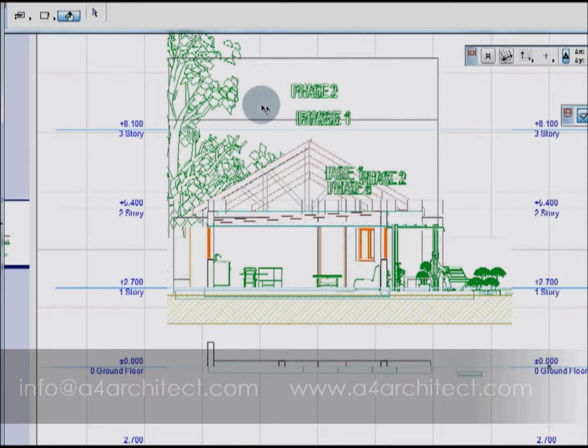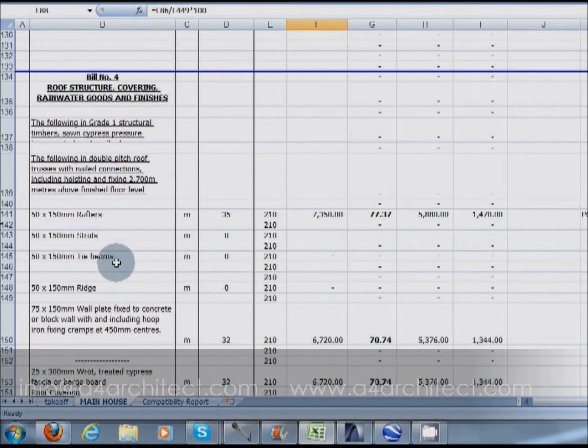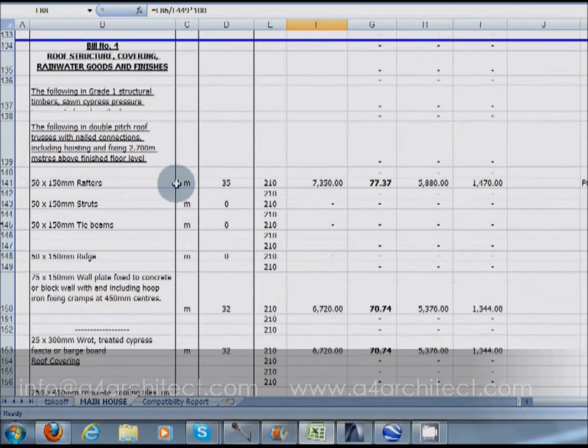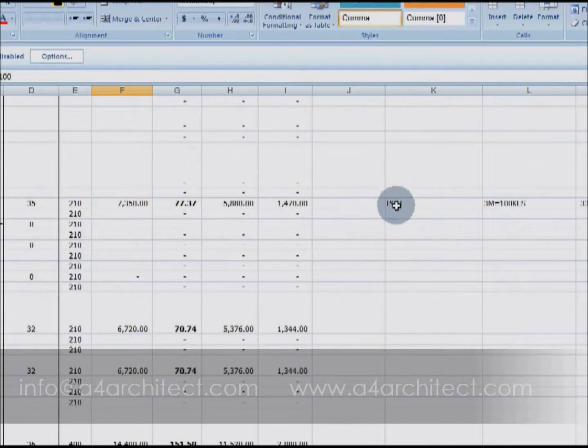Now we can look at the exact calculations of that. In the diamond house plan with the flat roof, you're talking about 35 linear meters of rafters, costing around 7,000 shillings, that is $77 US, and this can even be further reduced if poles are used instead of rafters.